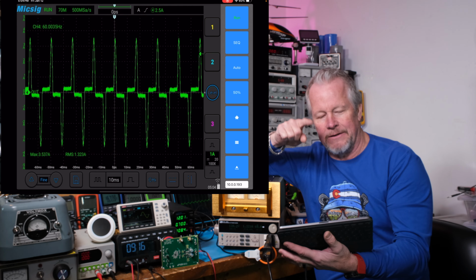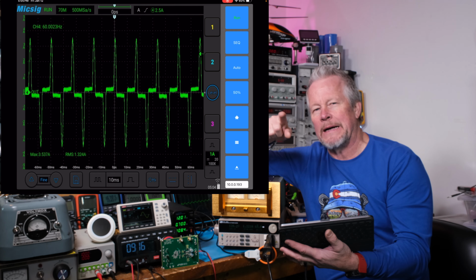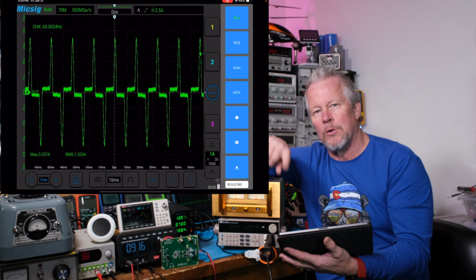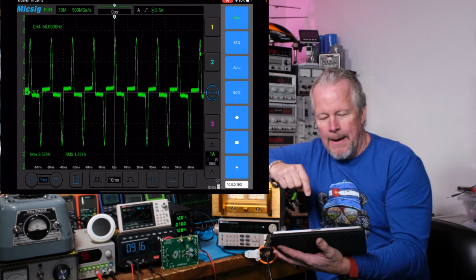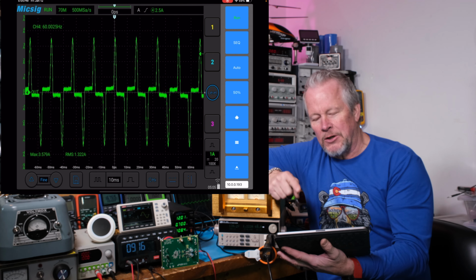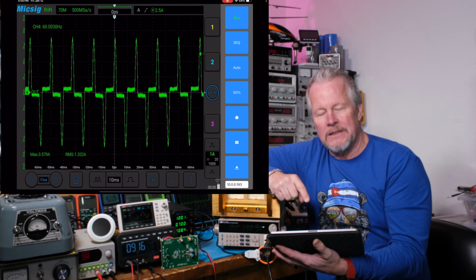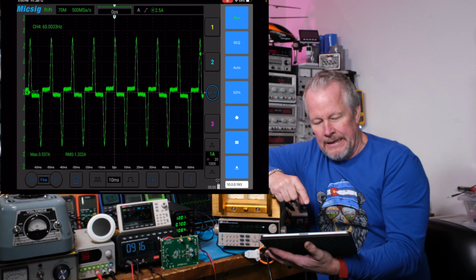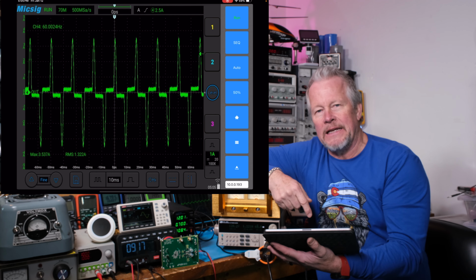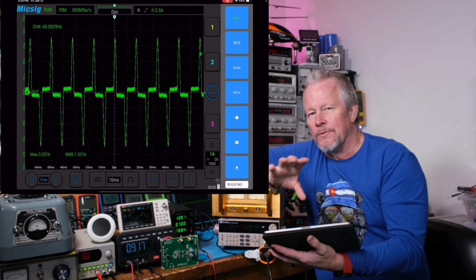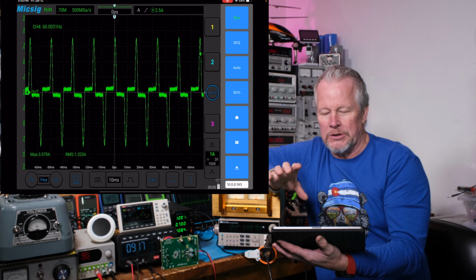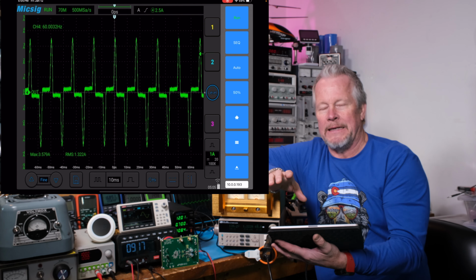You see a top waveform, bottom, and then you go back to the top, and once you go through a whole cycle, it's 60 hertz, right? But if we look at the spectrum of this, it's going to look like 120 hertz because we're getting spikes in the negative, spikes in the positive, and we don't care about that when we're looking at the spectrum. We're just looking at the spikes, and they're happening at twice the frequency, at 120 hertz.